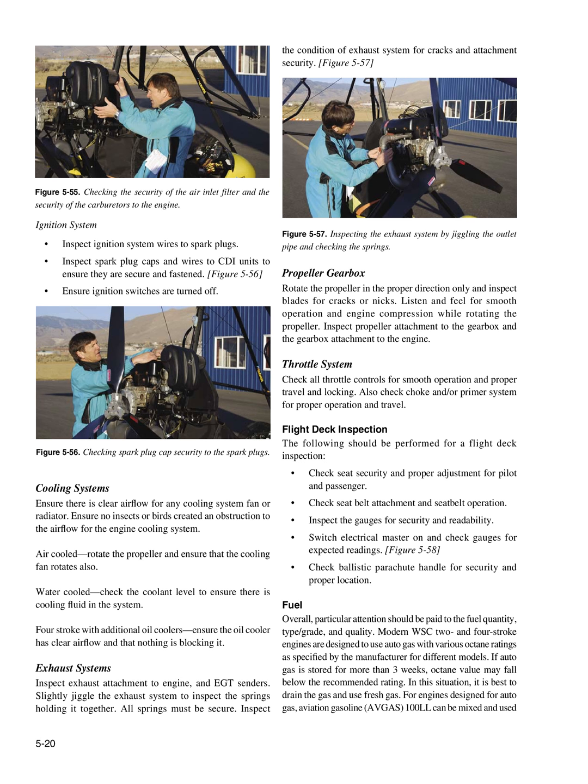Throttle system: check all throttle controls for smooth operation and proper travel and locking. Also check choke and/or primer system for proper operation and travel.